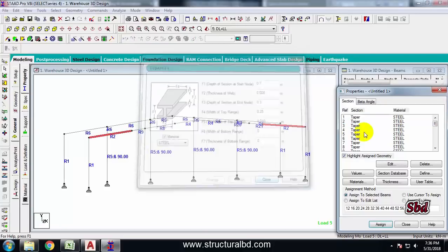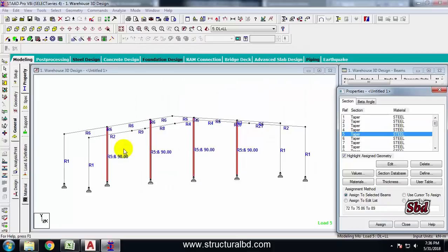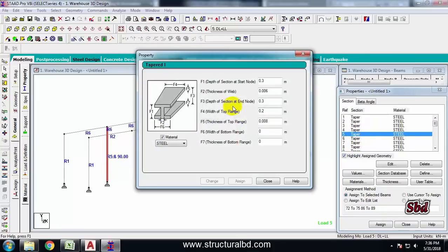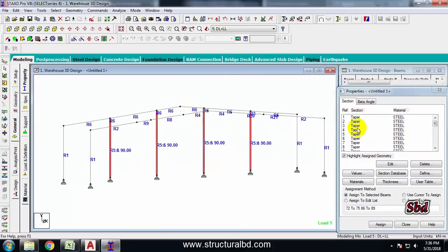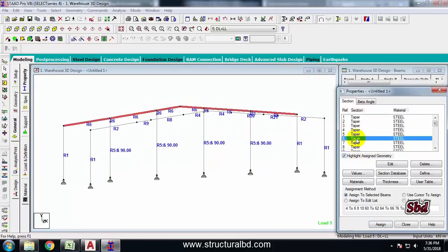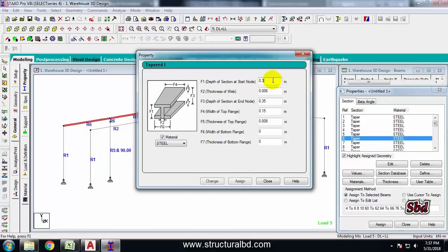Change yes. Okay, go below and now see this is my gable's column, double click. I want to reduce this one, I can use this is 1.5 and this is okay, change, close, and here is my gable rafter size, click here, this might be 300, 1.5, this may be 5, this may be 6.